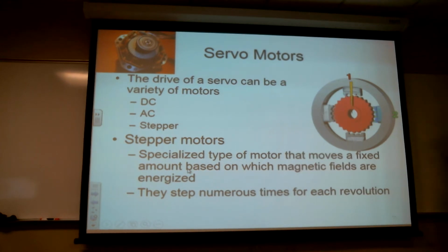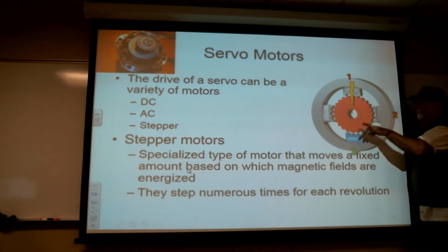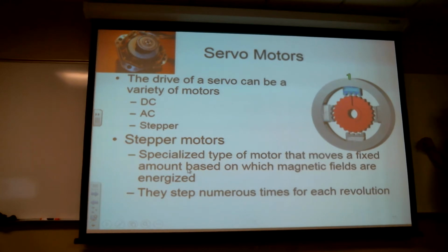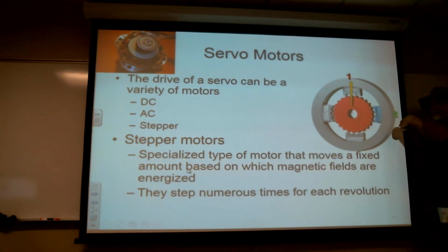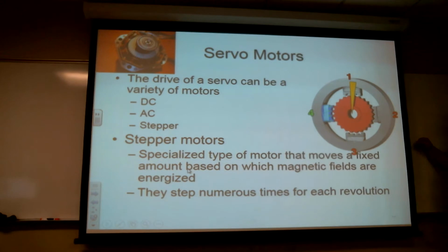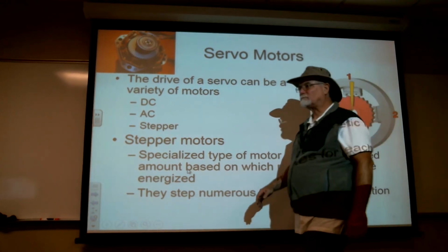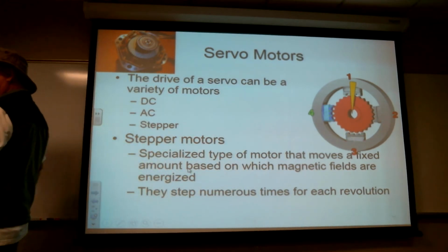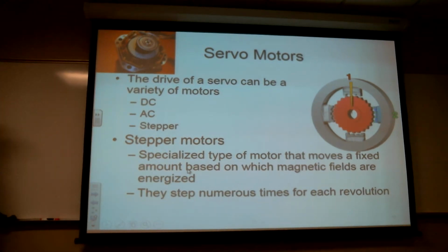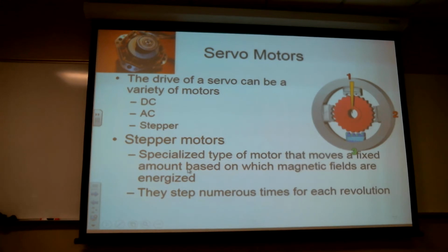And if I needed to be here and I passed by, that's okay, it's spinning so fast, I'll just wait till it comes back around again to that same spot, and then I'll get what I want from there. Okay, so that's one example of the stepper motor. In this particular case, I've got 4 individual fields that I'm going to control with the computerized circuit, turning each one on and off in some sort of synchronous manner.